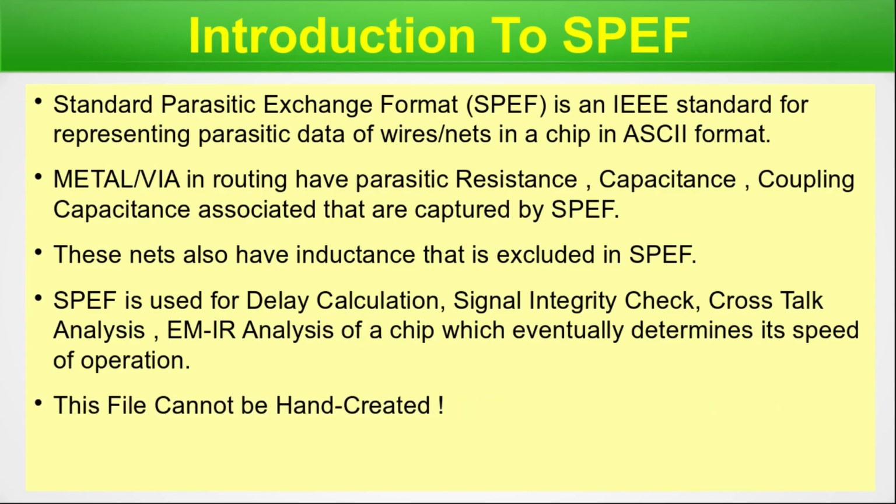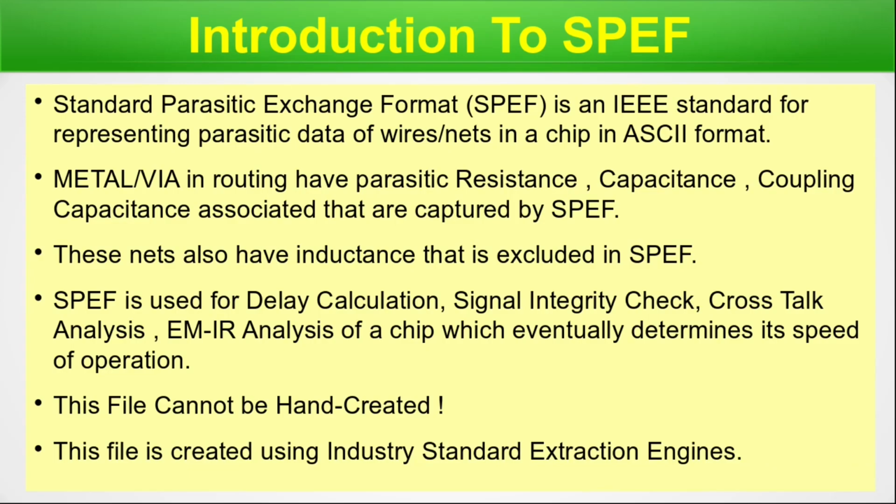This file cannot be hand created. So this is a very important point. We cannot write a SPEF file by our own hand. This file is created using an industry standard extraction engine. It's very important in the design flow where we are placing the extraction. You will see at what stage this extraction is done and how critical that stage is. So we cannot write the SPEF file by hand. So we are done with this particular slide.